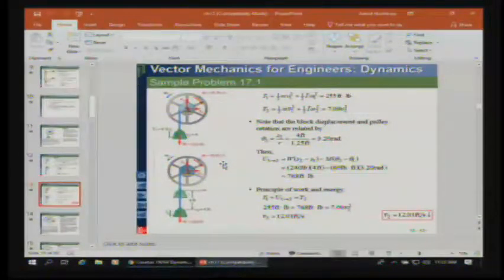Okay. Of course, we have to take into account the moment of the couple as well, because we're bleeding off energy that way. But the entire work is going to be the difference, and then we have to subtract out the opposing frictional work done as well. All right, so we add that together, and we can come up with the velocity of the center at time 2. So as you can see, there's a lot of parallels. They're longer problems. There's more involved in it, but you can draw on the work that you did with particles. You just have to think about the kinetic stuff, or the rotational stuff as well.